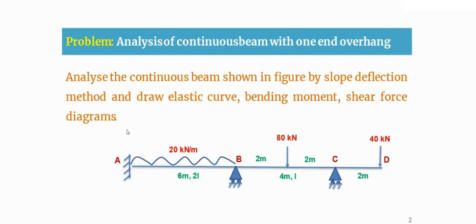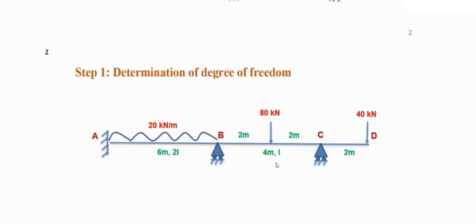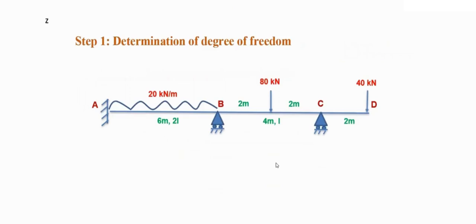Now in this lecture, you're going to analyze the continuous beam by using the slope deflection method, and you're going to draw the elastic curve, bending moment, and shear force diagram. Coming to step 1, you're going to determine the degree of freedom.